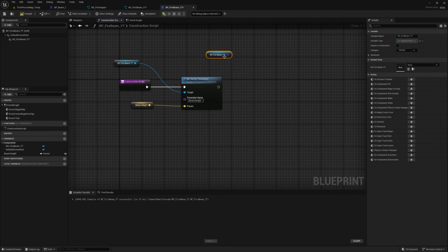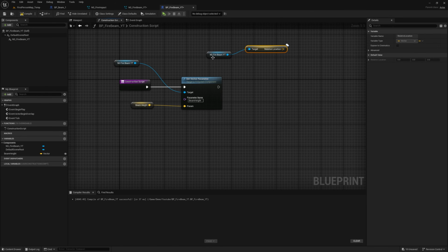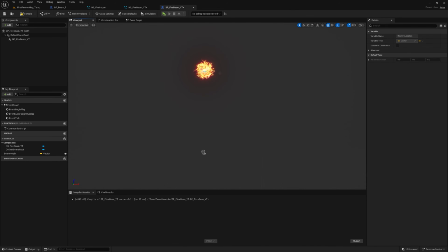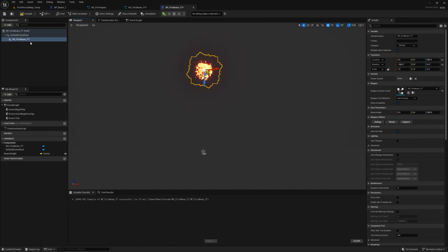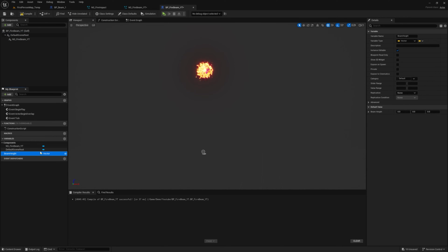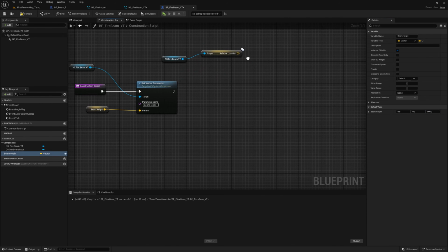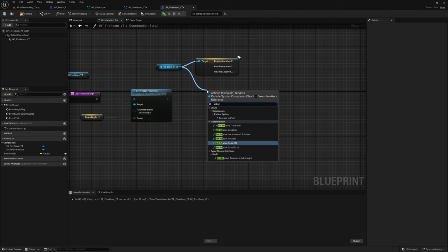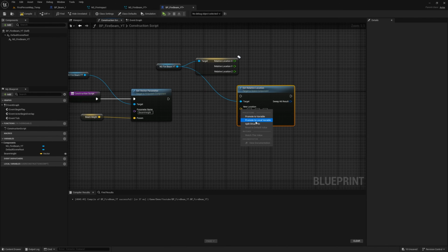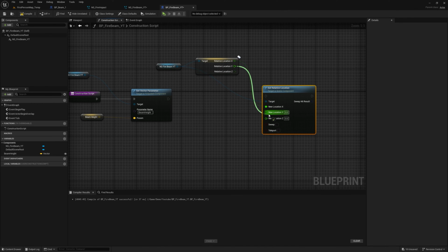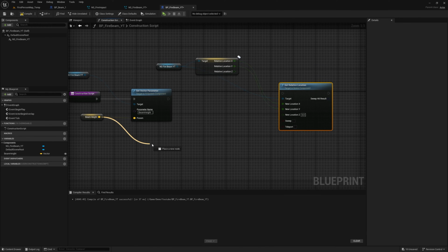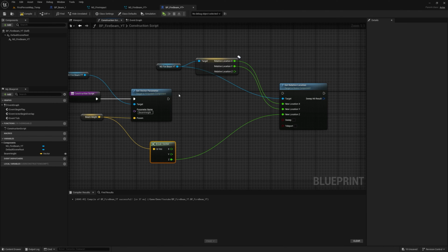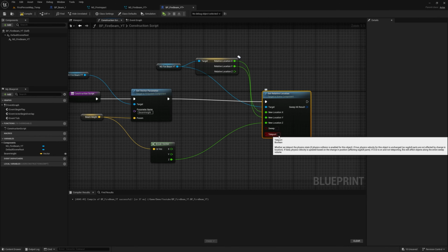Now drag this in again and get a relative location. So this is the location of the beam, so with respect to this actor. So it is a local location of this Niagara particle system within this blueprint actor. I now set the base height to like 900, and here we can just split this and now drag and type in set relative location and split this and connect the X and the Y. We don't really want to change that. And for the Z location we can break this and connect the Z here and connect this here and click teleport, so it won't do any collision checks.